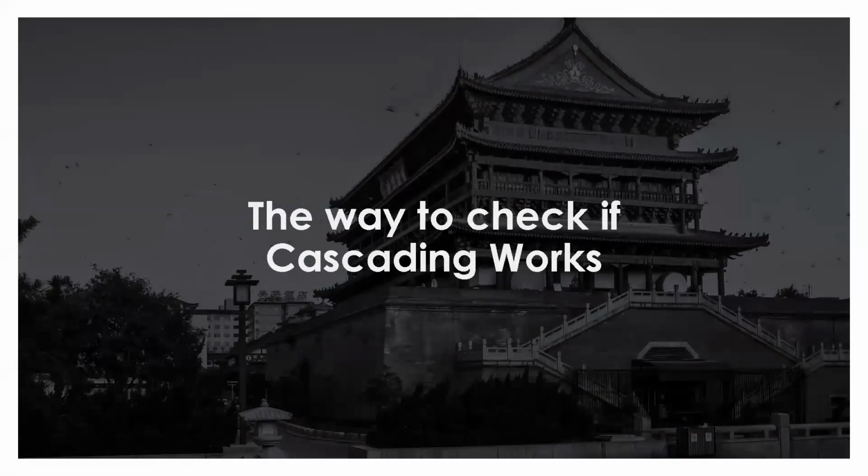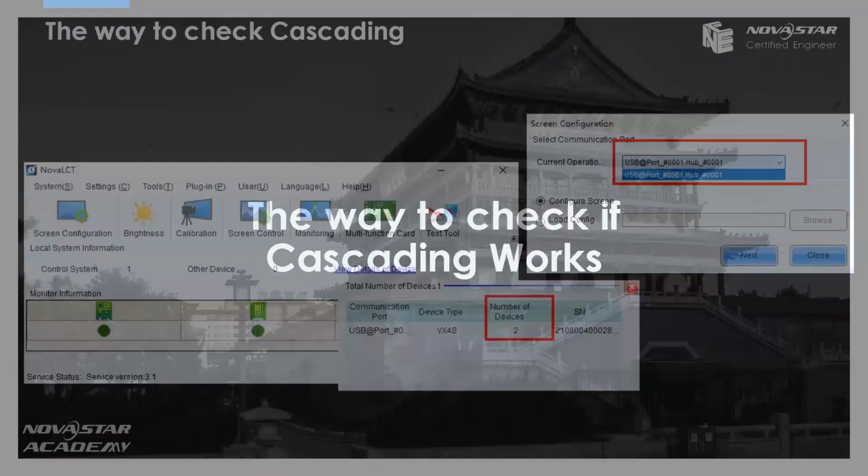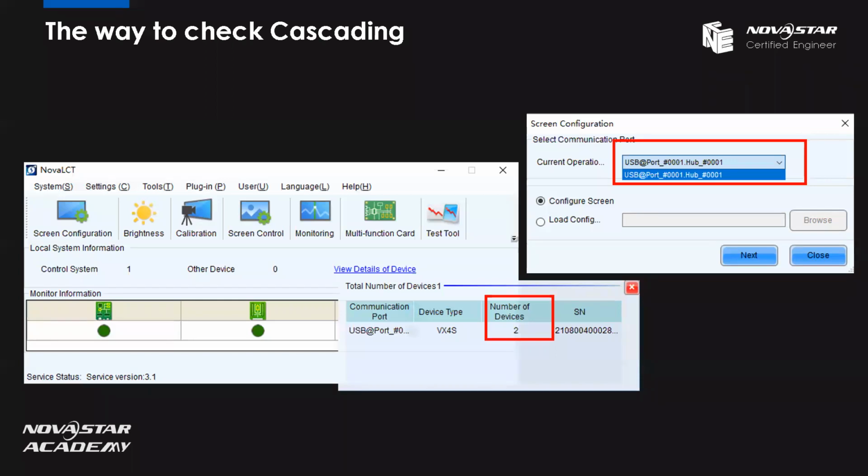But when we connect the cables, how can we know if the cable connection is good? How can we know the cascading is working? The way to check if the cascading works is in the software. In the NovaStar software, after we log in, we can see from the main interface that it is showing the control system is 1.